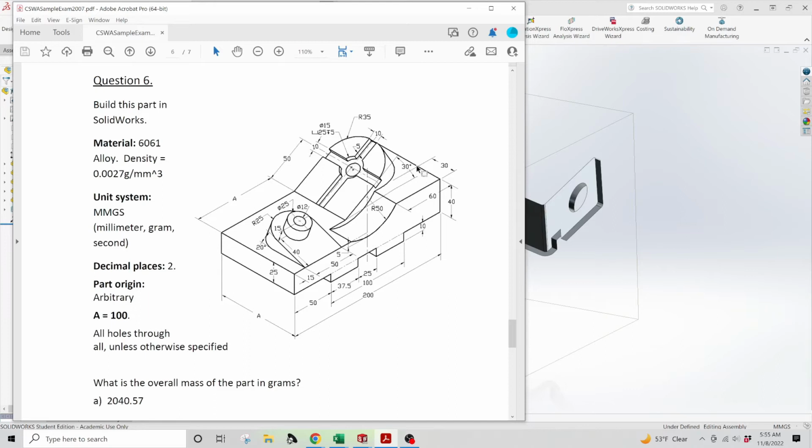So I'll do this part and show what I would suggest is the best opportunity. Starting with a single block and a rectangular extrusion is the longest, most excruciating possible way to do it. So don't do that. There are a lot of features here that you can capture in a single sketch.